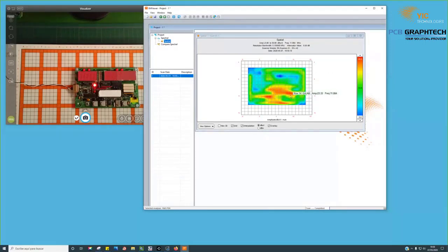The idea is, where is this area? If I look at the PCB, it's clear that the area is around the microcontroller, and it's going in this area, but you can see that this color is yellow. I have some kind of activity in this area. That is because in this PCB, this line that you see here is basically the ground. The ground is not in a ground plane. The ground is traces that are far from the forward lines. So we are creating big loops.